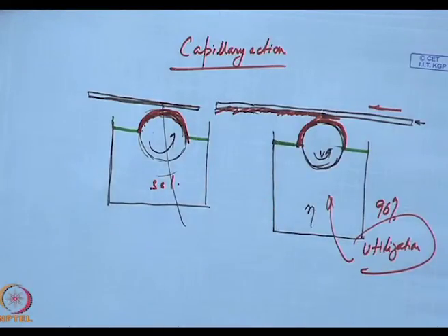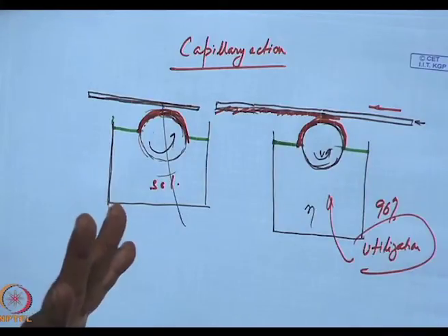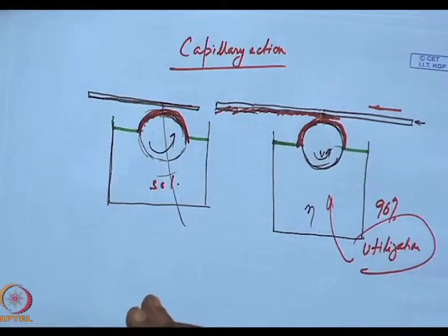Now, one of the things that alkoxide based coatings has given us is our ability to deposit say dielectric materials, barium titanate, on various substrates at very low temperature.